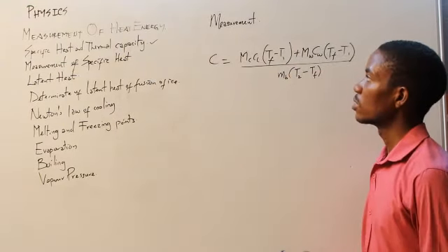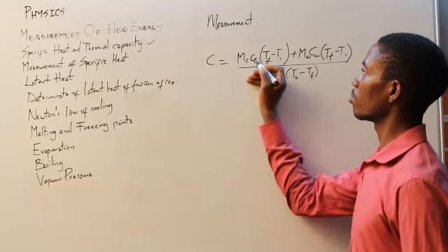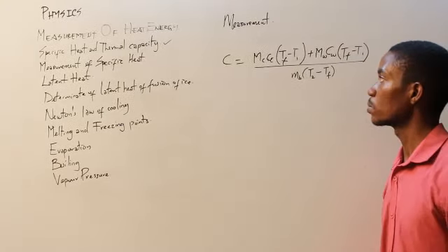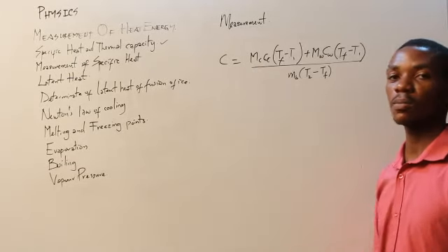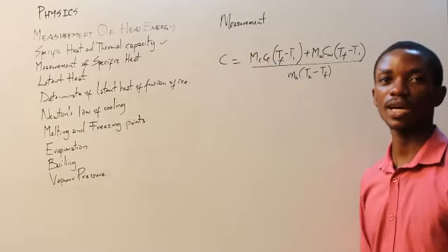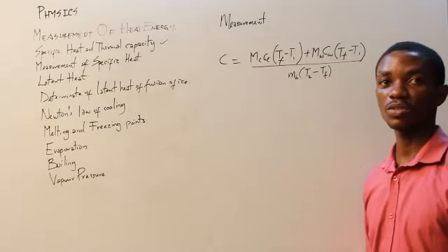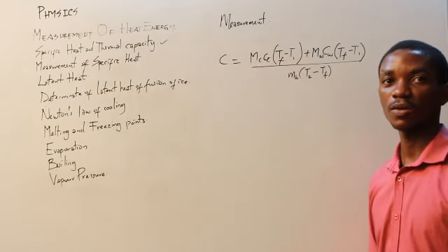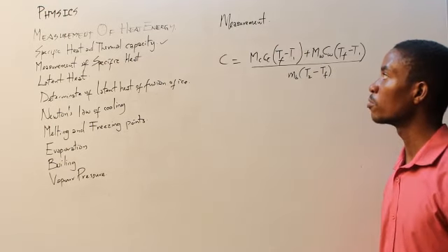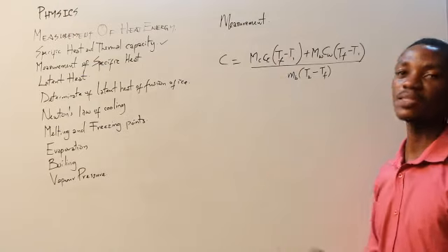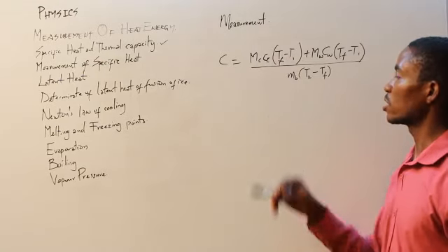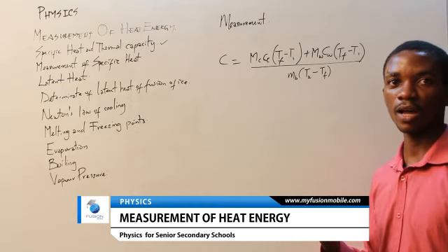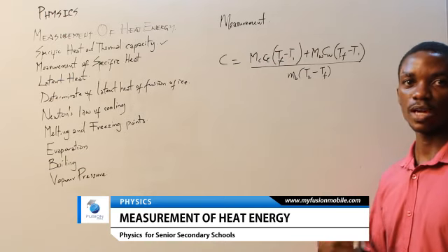To calculate the specific heat capacity of the solid, the expression above would help us out. Everything that has a C in front of it has to do with the calorimeter, the one with the W goes with water, and the one with the B goes with the body that we're trying to calculate the specific heat capacity of. The F means the final temperature, the 1 indicates the very first temperature, and the 2 talks about the temperature of the metal when it was brought to the calorimeter.